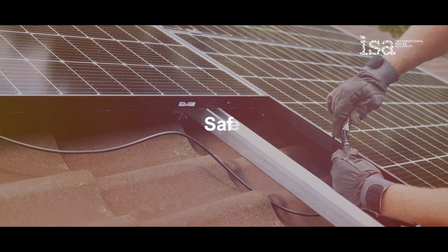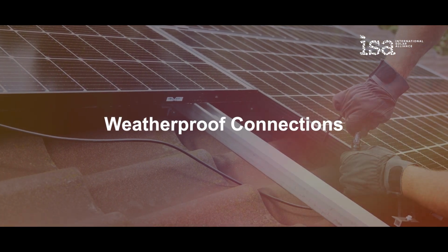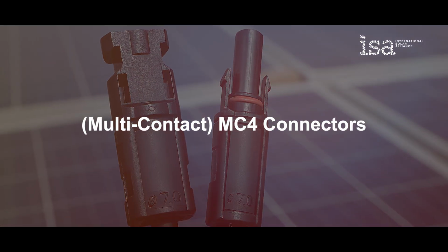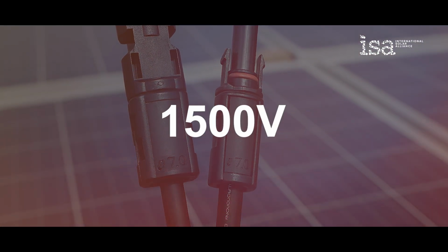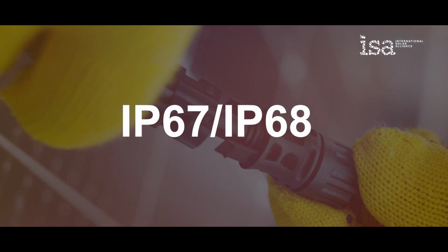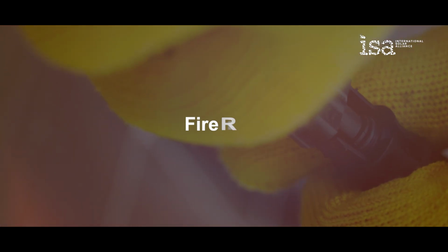Connectors ensure safe, reliable, and weatherproof connections, especially at module level. The MC4 connector is the global standard. It supports up to 1,500 volts, locks securely, and is rated IP67, IP68 for outdoor protection. Proper crimping is essential. Loose crimping increases resistance, heat, and fire risk.